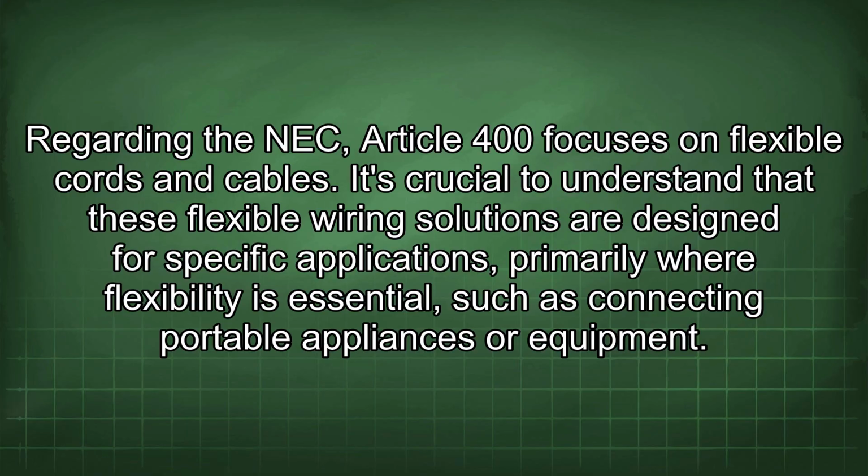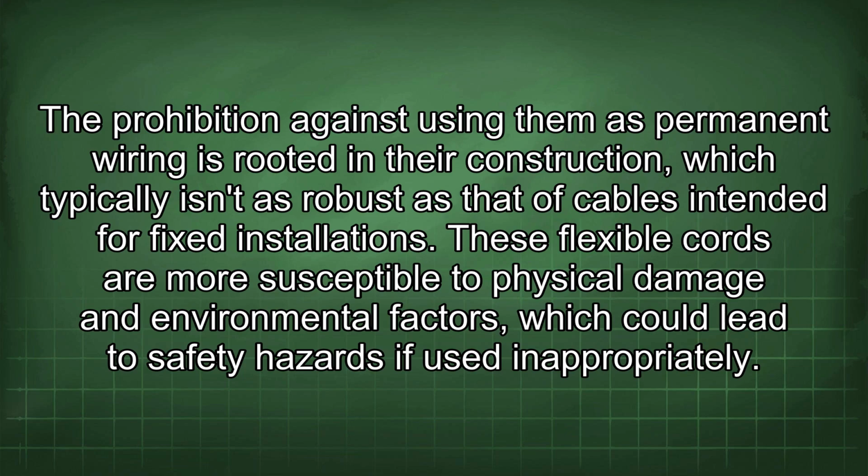It's crucial to understand that these flexible wiring solutions are designed for specific applications, primarily where flexibility is essential, such as connecting portable appliances or equipment. The prohibition against using them as permanent wiring is rooted in their construction, which typically isn't as robust as that of cables intended for fixed installations. These flexible cords are more susceptible to physical damage and environmental factors, which could lead to safety hazards if used inappropriately.